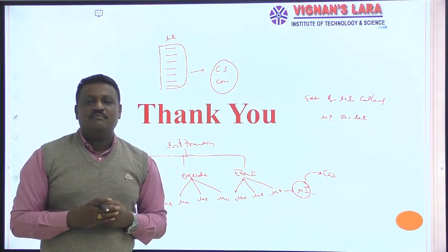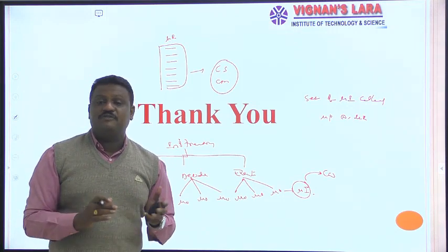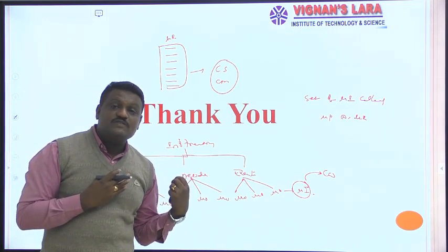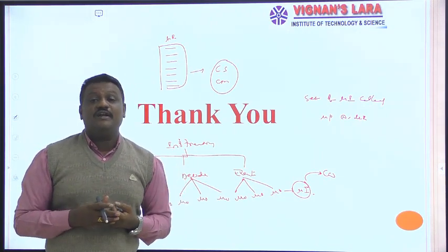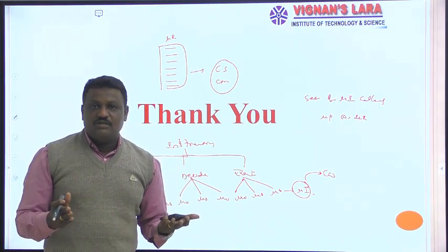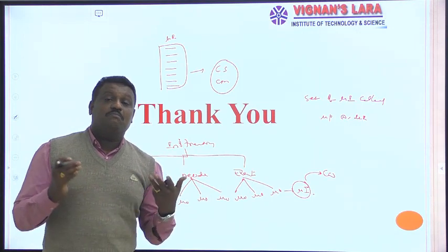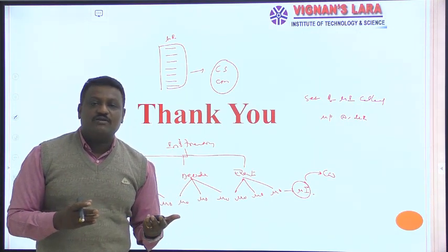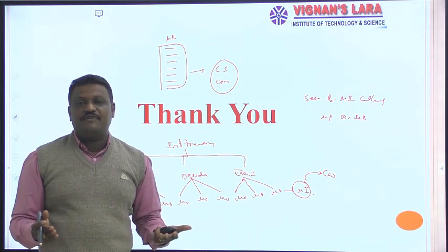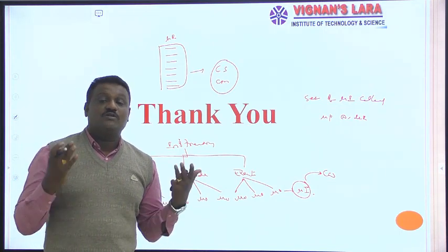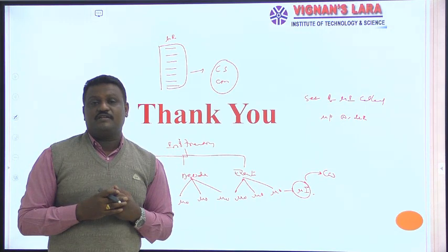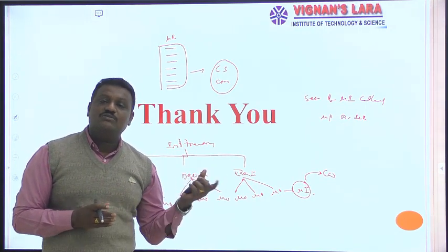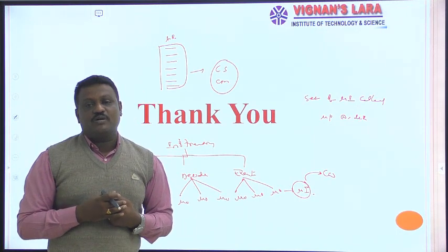I can do this, but it is not possible in the case of the previous control unit, that is the hardwired control unit. But the disadvantage is that the control signals are generated at a slower rate, because they are generated by execution of micro instructions. Execution of a micro instruction takes a certain amount of time, so the control signals are not generated at a faster rate. So this is the difference between the previous hardwired control unit and this microprogrammed control unit.